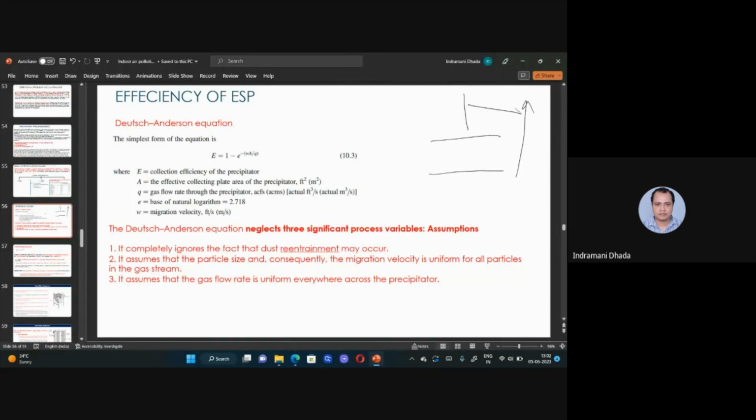The voltage difference we are giving is in terms of kV, kilovolts, and now you are passing the air, which has some dust and also some gases. When you give too high a voltage difference to these gases, the gases will be ionized. Ionized means you will get ions.